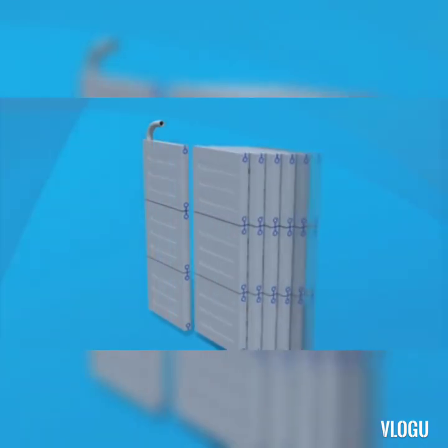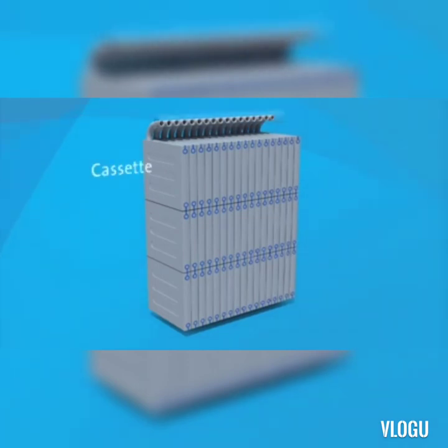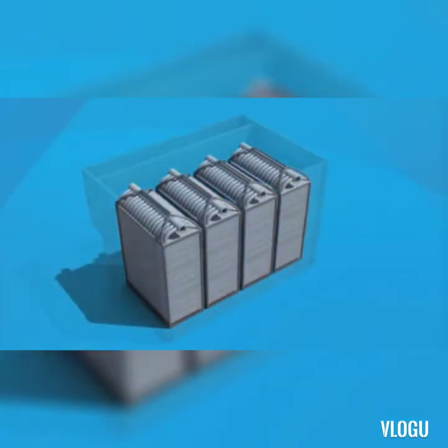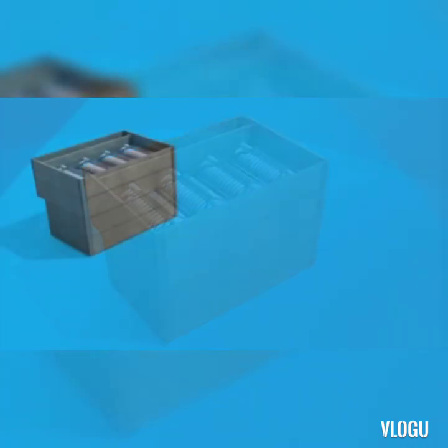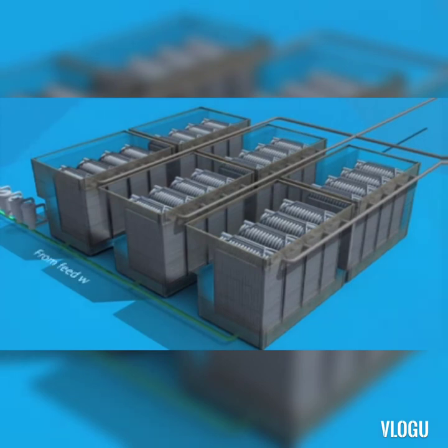Three membrane modules are loaded vertically to form a stack. Each stack has its own filtrate collection pipe. This design limits the number of individual connections in the system. There are 16 stacks, or 48 membrane modules, loaded into one cassette. A cassette is an assembly of membrane stacks. There are 4 cassettes arranged in one cell. There are 6 ultrafiltration cells. The design maximizes filtration efficiency.